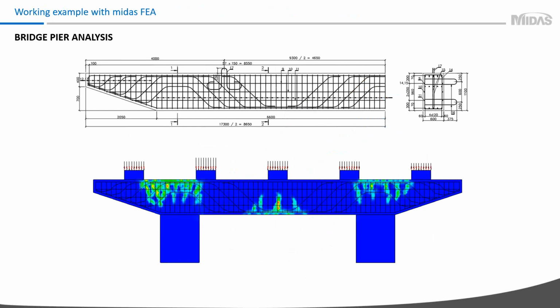I will consider a 2D model, which includes a bridge cap with a reinforcement frame inside the cap, with the bearing pads and parts of the columns. For the pier, I used concrete with compressive strength 35 MPa, and for reinforcement, I use Class A and Class B.